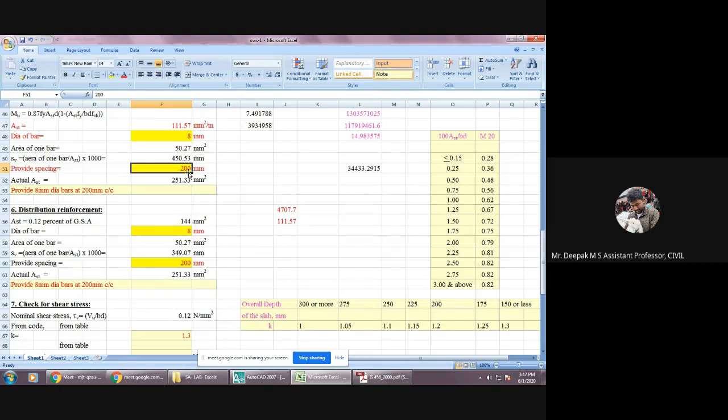So at the time of concrete placement, when the spacing increases more than that, there is high possibility that persons can walk on it and there will be excess pressure on the small area. If it goes beyond 300, then there is excess pressure in that small area where reinforcement is not present, so there is possibility of too many dents or it can even collapse.